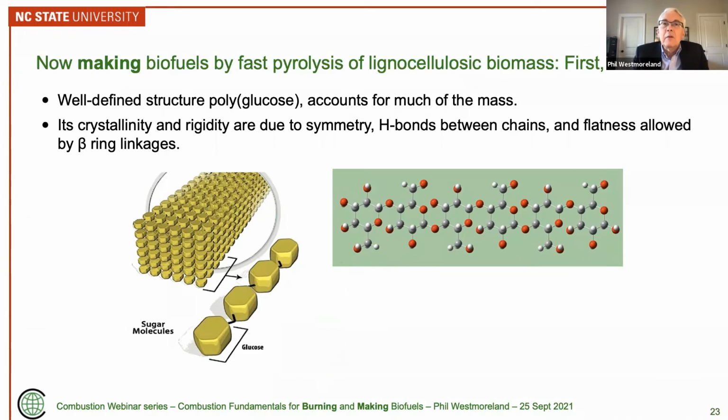We can do things like fermentation, other sort of destructions there. But as it turns out, right now, one of the most practical ways is just to do a fast pyrolysis and get the molecules out that are formed, and try to quench them to keep them from making gunk or solid.